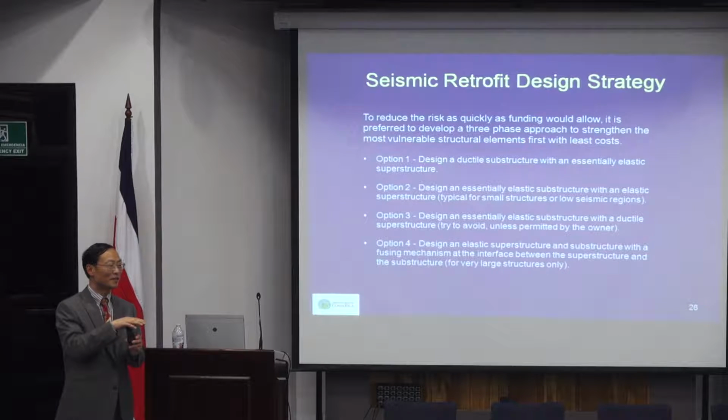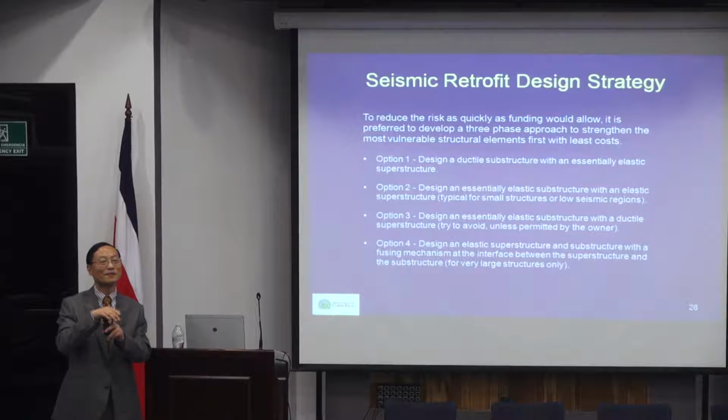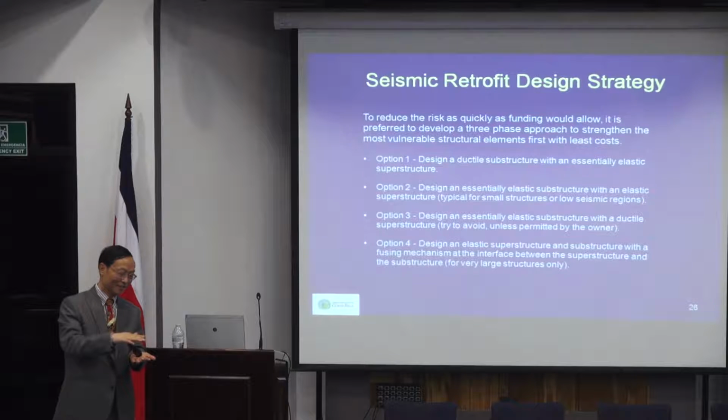Movement creates the inertial load, which is a function of the mass of my superstructure and also a function of my acceleration. But no matter what, if I have a hinge here, no matter how big the load, there's no load transferred to my footing at all.